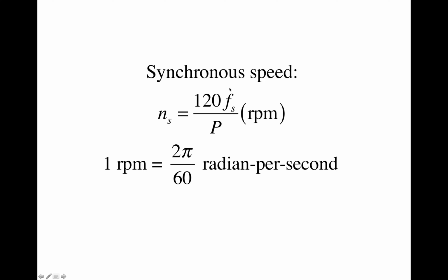And it is proportional to the frequency of the three-phase alternating current, and it is inversely proportional to the number of poles per phase. And this part is probably counterintuitive at first glance, right? It's actually inversely proportional to the number of poles per phase. And we discussed why it is so. So if you increase the number of poles per phase of the current, then you actually reduce the rotational speed of the magnetic field inside the stator.